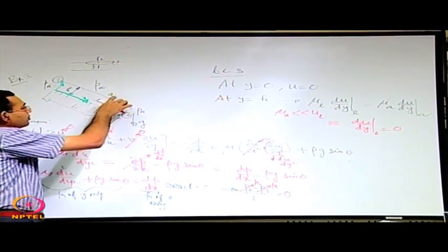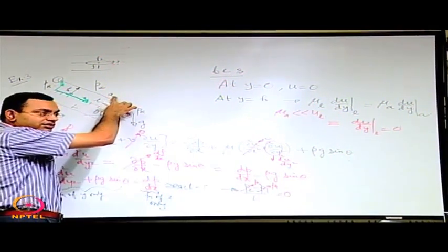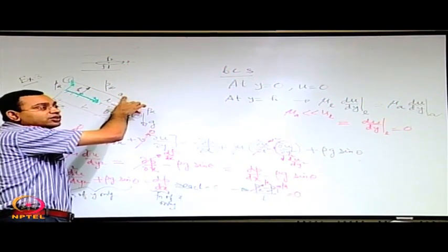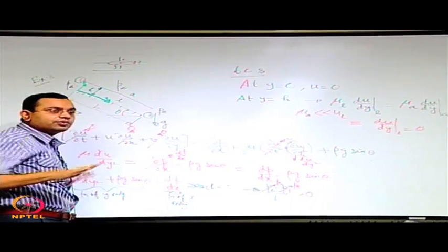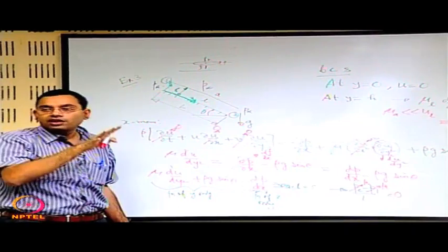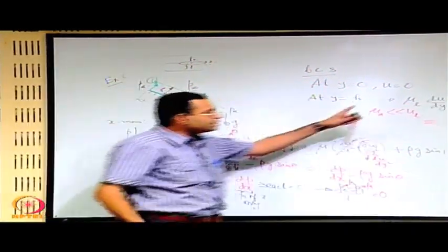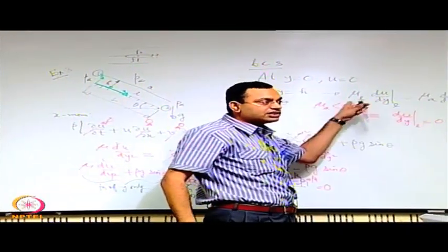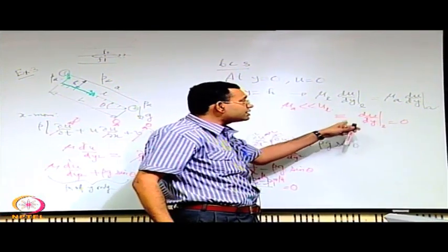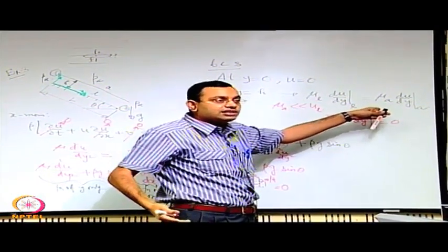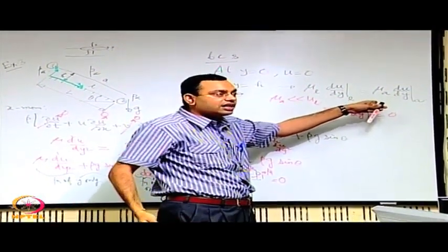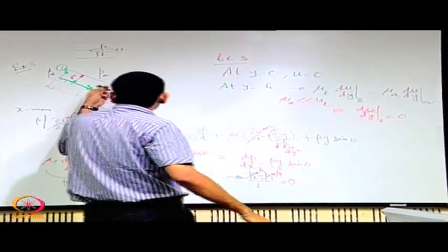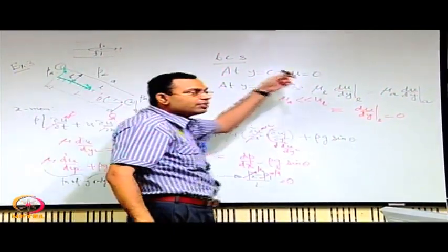If I now replace air with another liquid, then you will be in trouble, because if you do not know the fundamental principle from which it comes out, you will still write a wrong thing. So the important fundamental principle is continuity of the shear stress. Here the special case is just a coincidence that air has much less viscosity than the liquid, say water. So roughly like 1 by 1000.